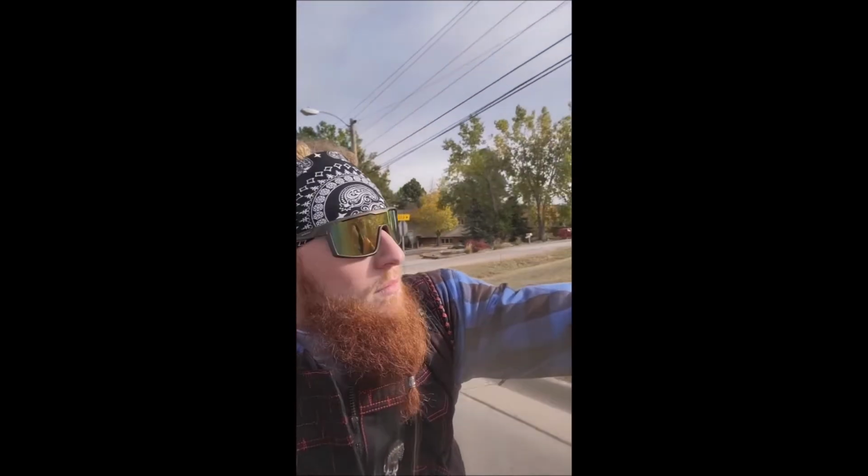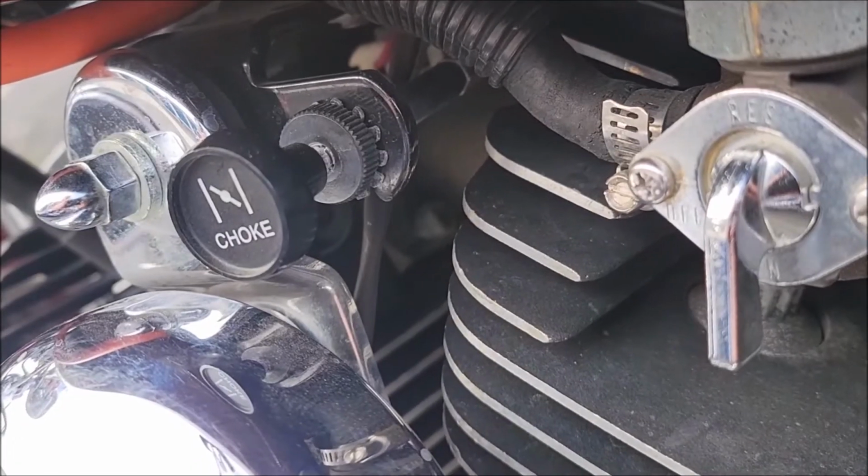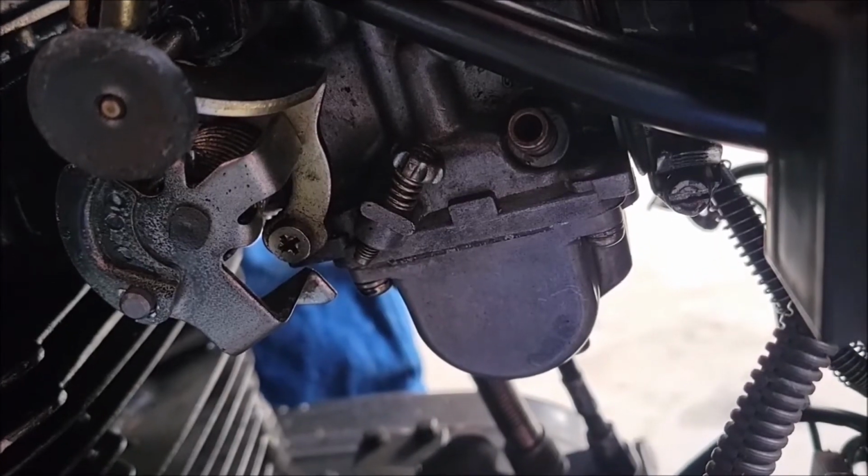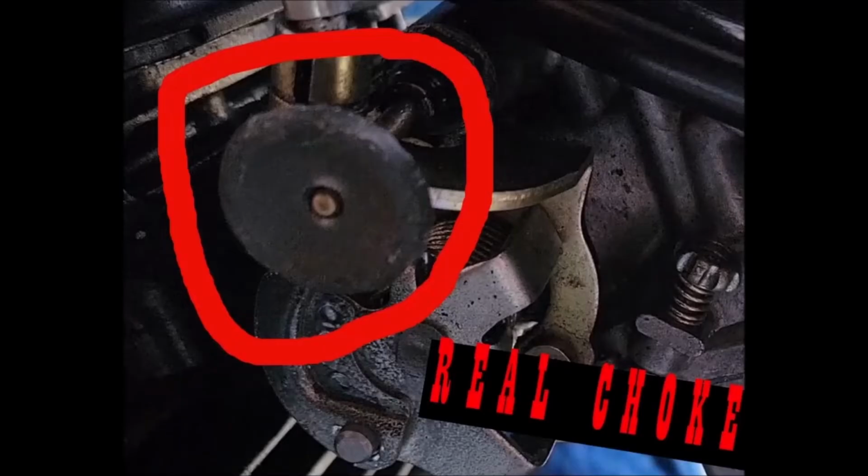Because of this, most carbs will have secondary ways to add or remove air and fuel. On your particular carburetor, you may either have an enrichener or a real choke. An enrichener is a simple circuit in a carb that allows more fuel on a cold start via an extra jet. This adds more fuel to the equation, making a richer air-fuel mixture. A choke is an actual plate that reduces airflow. The choke reduces the amount of air, creating a richer air-fuel mixture.